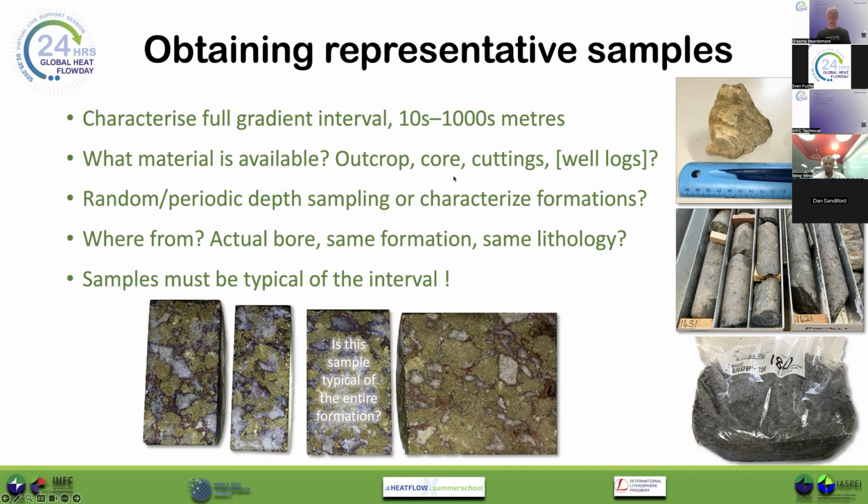Ideally, we have core. Core is generally the best material to work with for thermal conductivity measurements. Cuttings, so the drill grindings that return to the surface during the drilling program, are a far worse second best to core, but if that's all we have, then we can still try to get thermal conductivity measurements from the cuttings of the formations that have been brought back to the surface. And if all else fails, maybe electrical well logs. We may be able to infer physical properties like thermal conductivity from the electrical responses recorded on well logs in the bore.